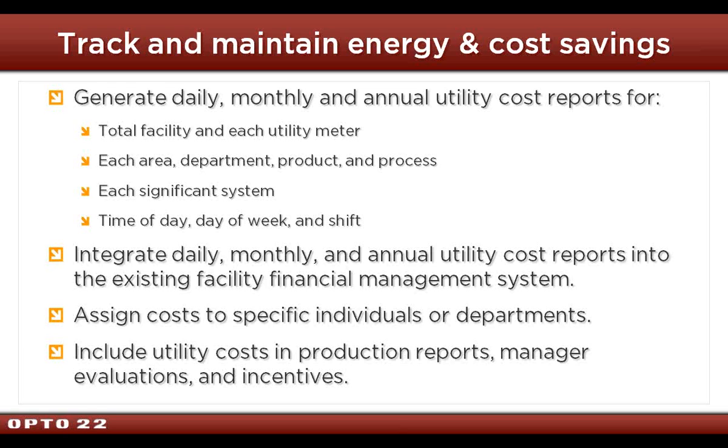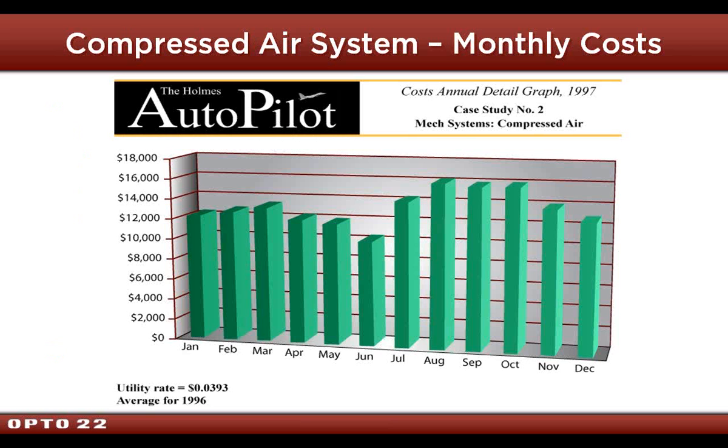We found chillers, in almost every case, twice as big as they needed to be. And so they limp along most of the time running at horrible operating efficiency, with the pumps and the fans using more energy than the chillers themselves. Once you have the data, then you got to display it in a meaningful way.